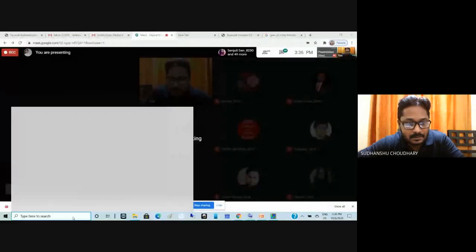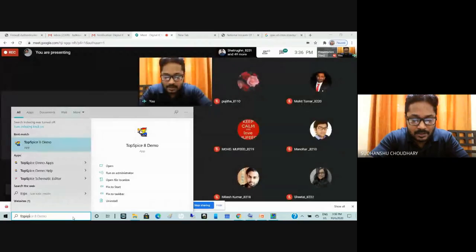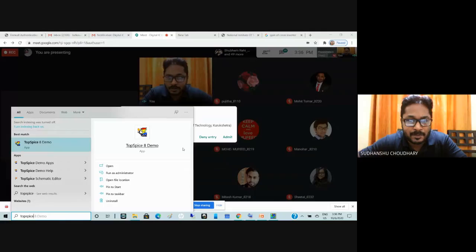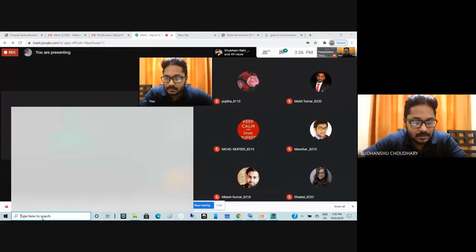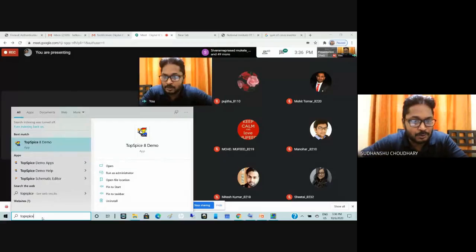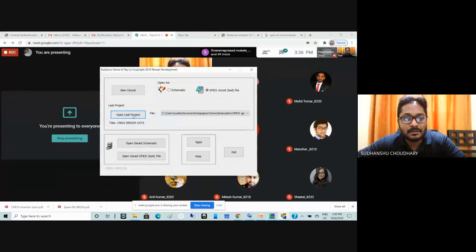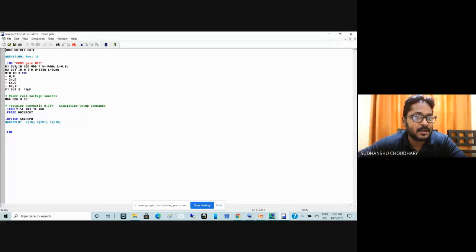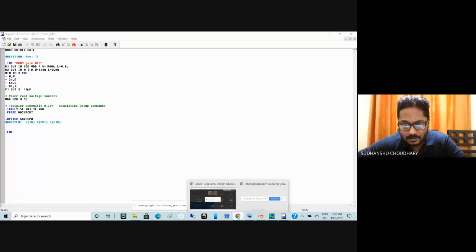Only PPTs were visible. No issues. Now I think you can see my desktop, right? So let's say I have TopSpice, another Spice simulator, so you can also download it if you wish. So maybe I have already written the CMOS inverter, right? For this CMOS inverter, either you can write a Spice code like this, or maybe you can simply connect the PMOS and NMOS and then generate the circuit here.